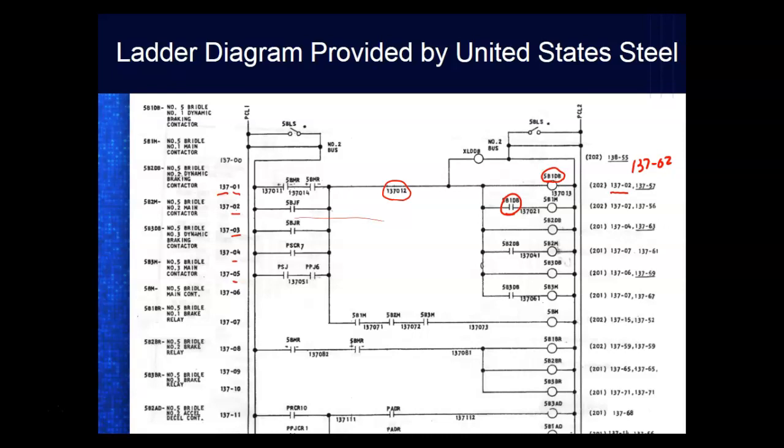So what we do in motor controls is we give lines numbers. We don't give rungs numbers. We give line numbers. And this is one thing that's really big and different in PLC. And then we give a relay coil a name, and over here we put the line number where the contacts that thing controls are located. This has got a normally closed contact.